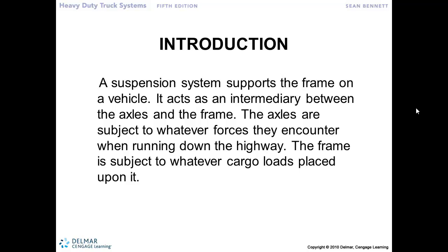So the suspension system is the connection between the frame and the axles. All the weight that is supported by the frame, we're going to transfer that weight and that force down through the frame to the axles through the suspension, right? And then axles to the wheels, to the hubs, to the tires, out to the pavement.